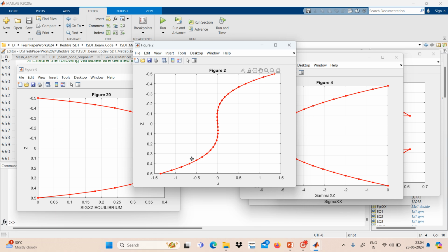Okay, so it is getting warped, varying in a higher order way, not linear but in a cubic fashion. So this is the higher order shear deformation theory, where the warping of the in-plane displacement varies cubically. The plane section is no more plane, it is now warping in this cubic way.